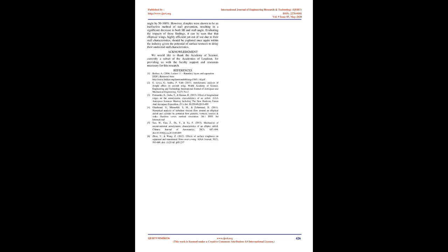However, in Figure 8 and Figure 10, the bump and groove wings at the same angle of attack show little to no boundary layer separation. The airflow around these cross-sections shows minimal evidence of a separated boundary layer, supporting the data that the stall angle was indeed delayed by the surface texture.